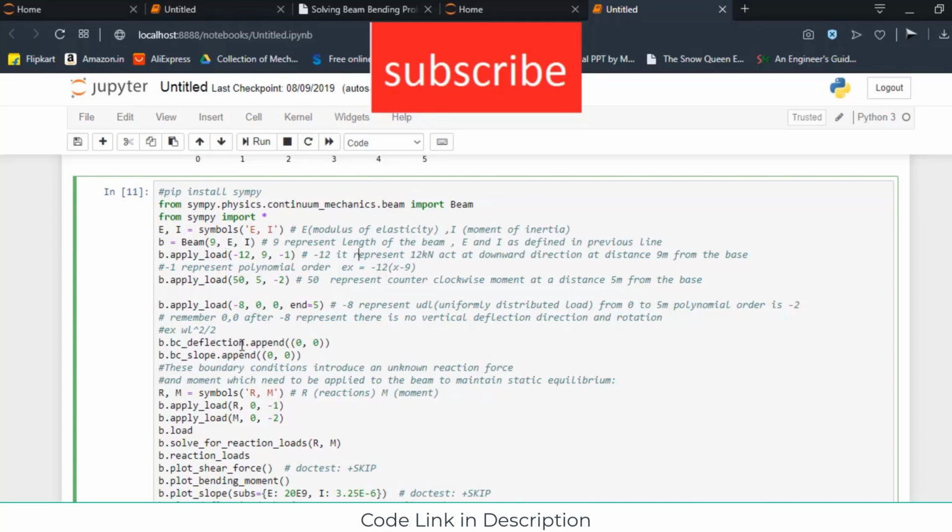Now B dot BC deflection dot append and B dot BC slope append 0, 0. These boundary conditions introduce an unknown direction force and moment which need to be applied to the beam to maintain static equilibrium. Now here R and M represent reactions at the end, and M is the moment. B dot apply dot R 0 minus 1. Here are the codes.